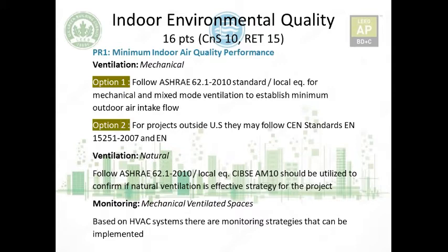Now for the natural ventilation, you have to follow the same 62.1-2010, but there is CIBSE AM10 that is needed because you have to show or confirm if natural ventilation is the right strategy for your project or not. It depends on the climate. In certain climates, natural ventilation cannot be used.